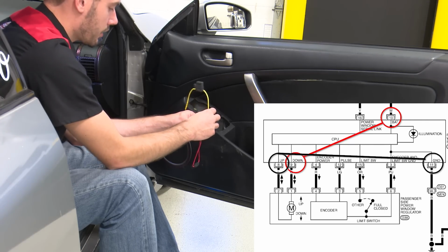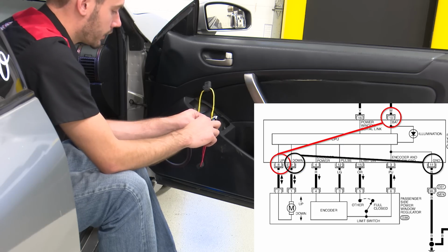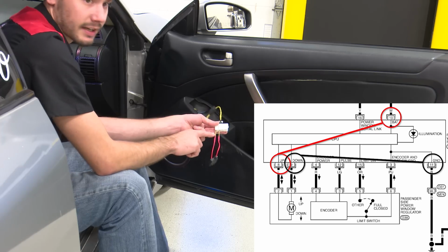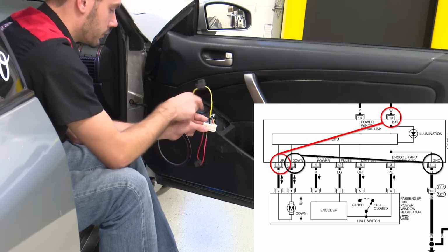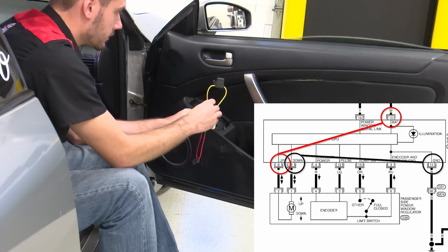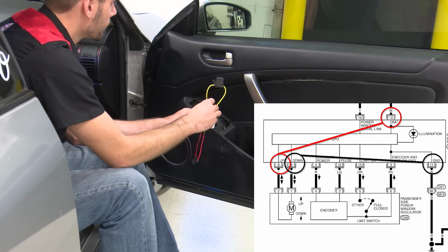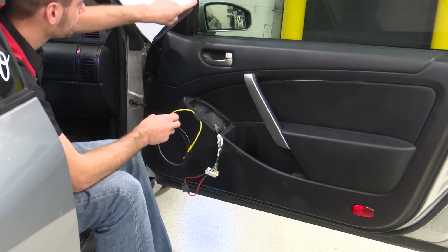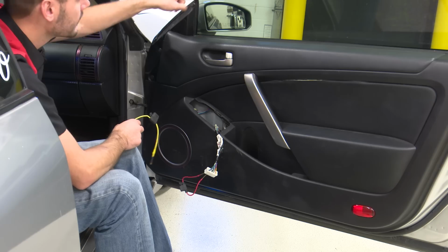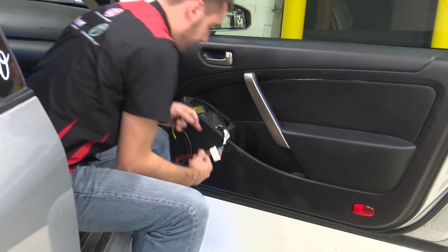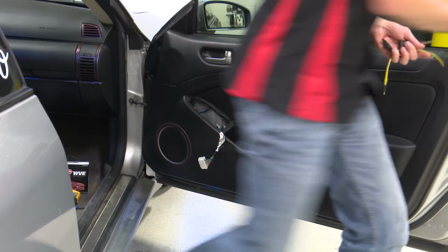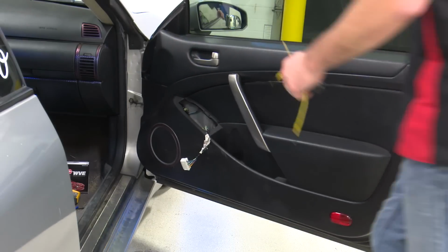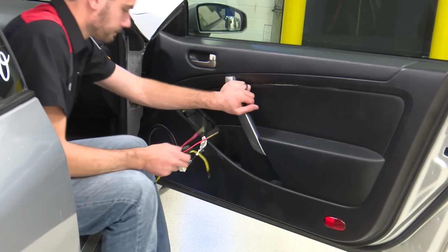Now, if we swap these around and we run our ground to our green wire and our power to our blue wire, the motor should go back up. So we'll just disconnect on this side of the connector. We'll go now here to green. There we go. So our motor goes all the way back up, and just note that it stops up here at the top. It's tight against my molding right here on the body. So this window is all the way in the upmost position. If I close this door now, we could run into an issue with the glass hitting the body, okay? Just take note that we gotta be really, really careful.